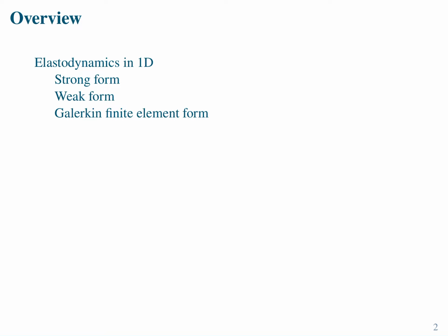Not really, because if you think about the dynamic equilibrium equation, you have essentially the displacement, velocity, and acceleration. So you have one equation and three unknowns, right? So you want to combine this dynamic equation with something else. And so we're going to discuss Newmark's family of methods, which is one way of solving the dynamical systems.